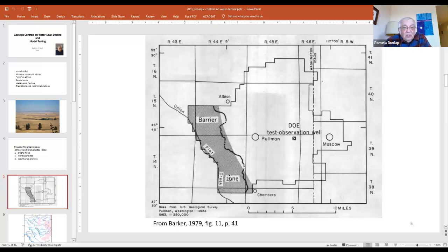Creek area. I believe, and some other people also follow that thinking, that in this area the basalts that can carry the lower aquifer water have poorly developed intraflow zones, or something's out there, igneous dikes that are known to exist in that area. Something is slowing the water down, slowing the groundwater movement to the west. And one of the problems has been there are no deep production wells out there. We do have observation wells, but no deep production wells.